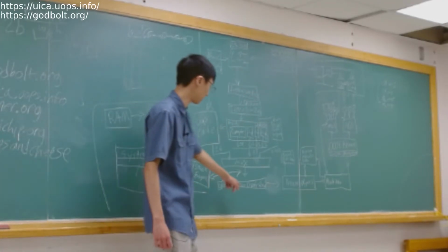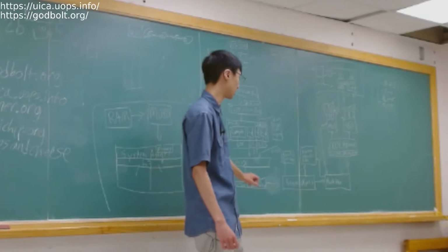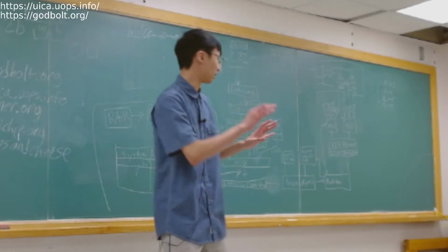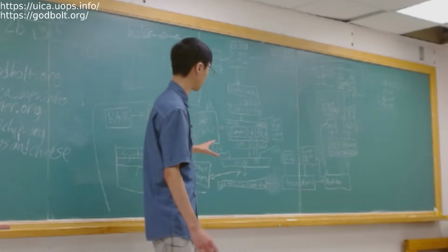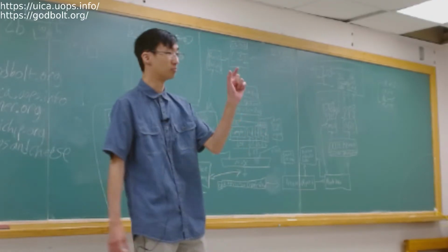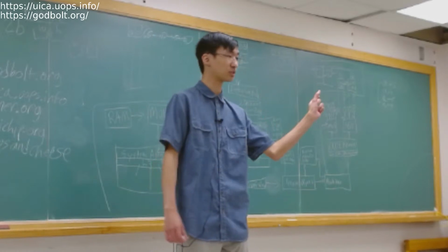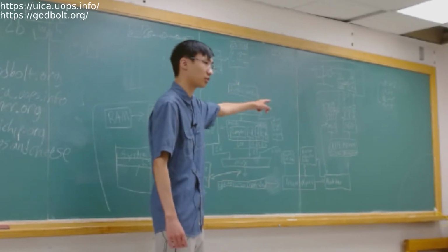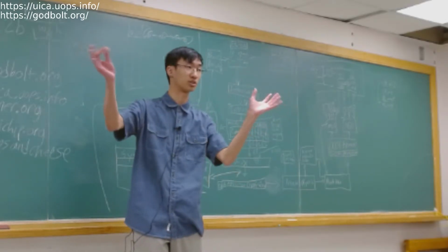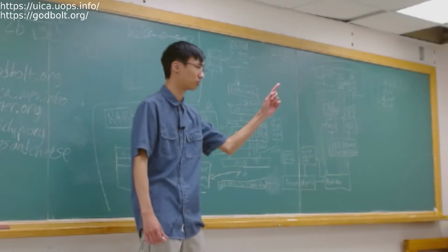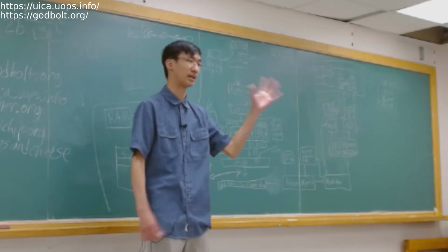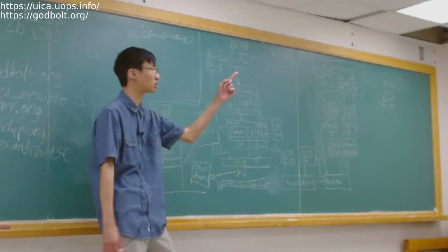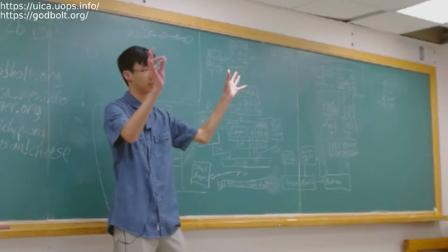The other thing that I forgot is optimizations inside the decode queue, or I guess the rename part. So after decode, we also have this idea of move elimination. Obviously, every time we modify a register, we make a new register to save it in. So if you're going to copy a register to a register, why would you make a new register when that register is always going to be the same? So you're not going to do that.